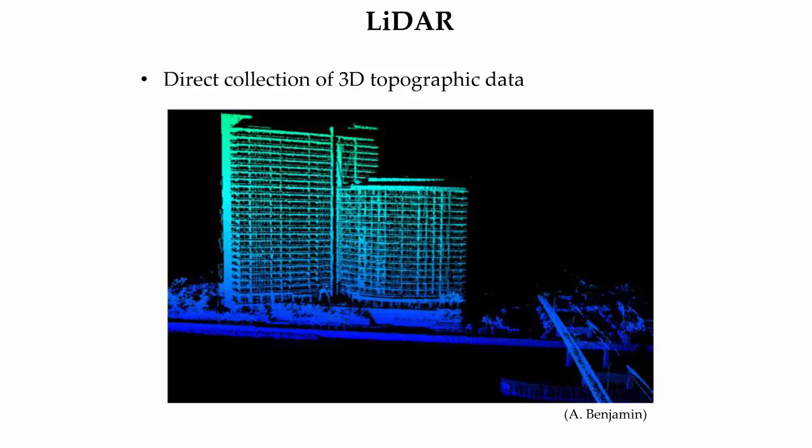To derive the same 3D data, traditional photogrammetric methods require additional intermediate steps, including the construction of stereo models from aerial imagery. As a mainstream mapping technology, LiDAR data is collected routinely from both terrestrial and airborne platforms. This image depicts LiDAR data of a condominium building on the Intercoastal Waterway in Miami, Florida, from a terrestrial LiDAR scanner.